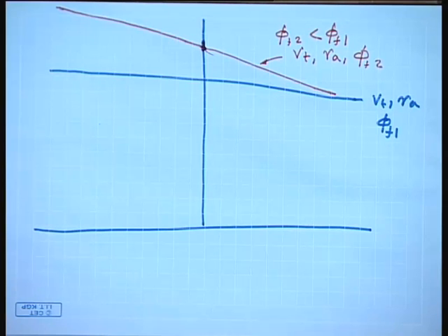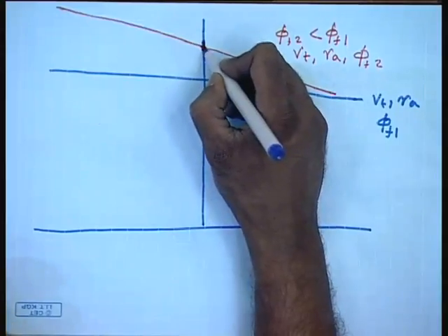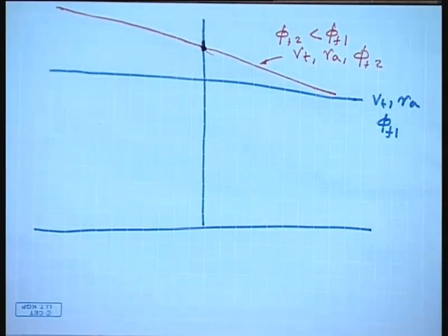It will be interesting to find out how far we can reduce this field flux. In fact, we cannot increase the field flux very much because of saturation. The machines almost always work at rated flux. We can reduce it, but cannot increase it very much. So, we will consider only decrease of field flux and not increase.